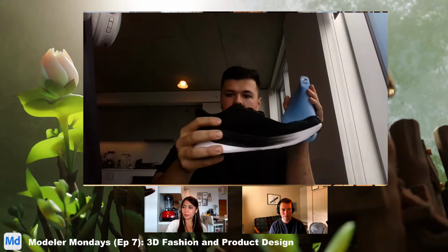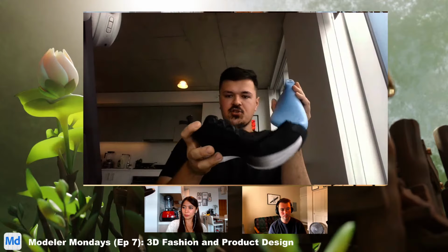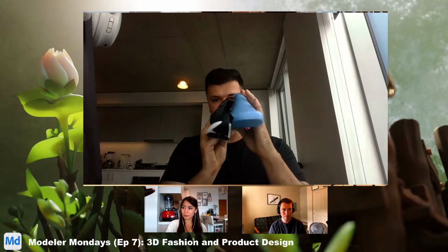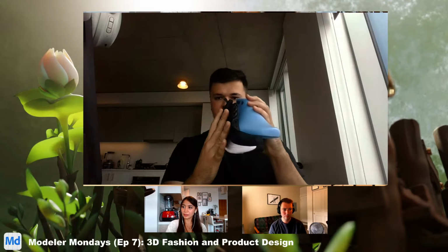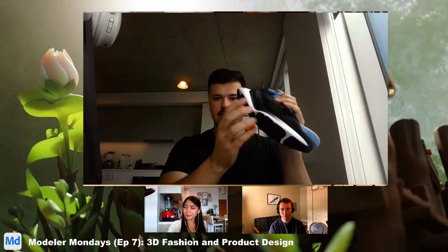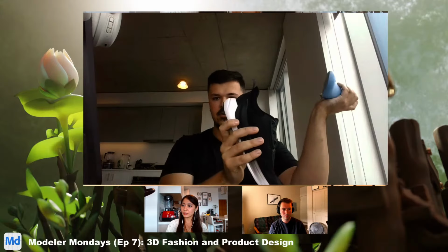When they're building shoes, they have the upper, all the fabric of your shoe laid out flat. They stretch the upper over this last, so the fabric is sitting on the last like this. Then they take the sole, which is all the foam and rubber, adhere that to the bottom, and pull the last out. And then your final shoe is made.